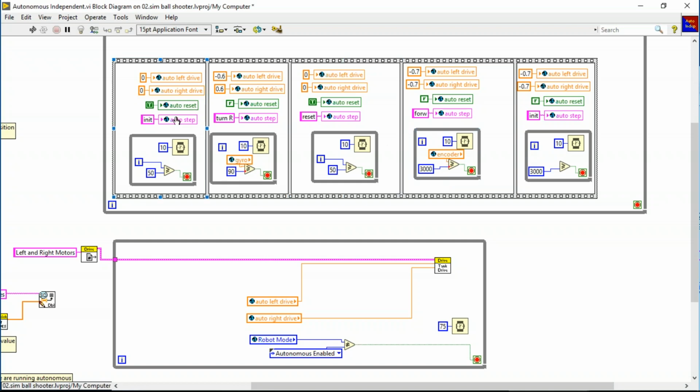Okay, so I'm going to initiate everything, zero my motor, reset the encoder and the gyro, then release the reset, go forward on the left drive, reverse on the right drive, turn right until my gyro is greater than 90 degrees, stop everything, reset again, then release the reset, go forward for 3,000 pulses, and then over here I want to stop.